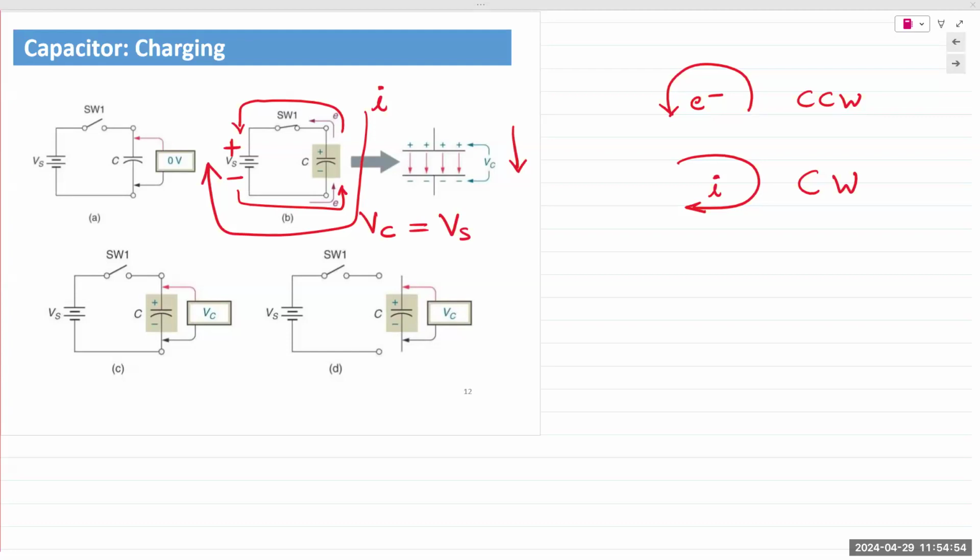Electrons are not flowing through the capacitor. Yet we do state that the current is flowing through the capacitor. When you first start out, it's hard to reconcile the two. See, electrons are constantly moving, right? So if electrons are moving, with the exception of those two tiny plates, current is flowing through the circuit. Yes? So we state current flows through the capacitor.